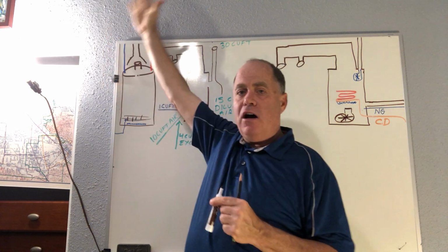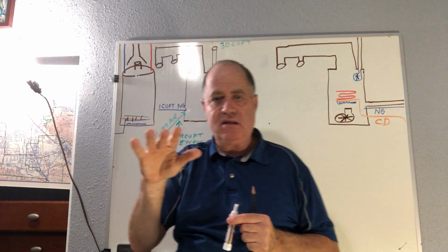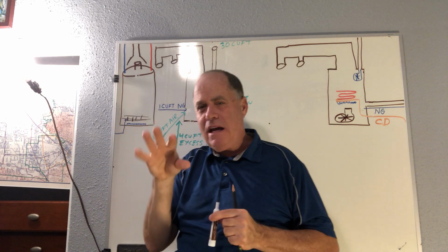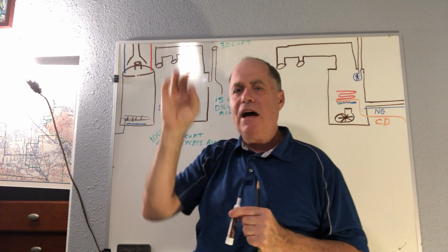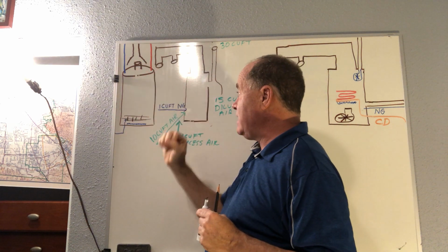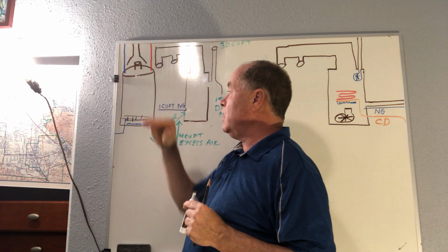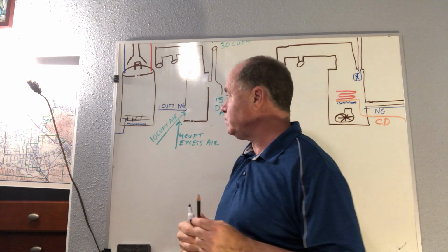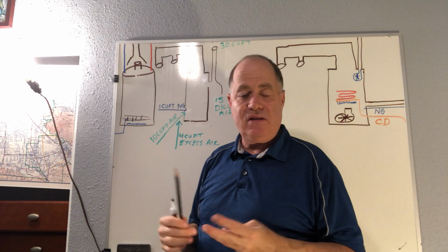So to help it move along and not condense, and sometimes you may hear in an old hot water heater or a furnace a sizzling sound. When it first starts up and gets going, you may have a little bit of condensation where water droplets drop out of the flue pipe, the chimney pipe, back down, and you could hear it sizzling. We don't deal too much anymore with natural ventilation type furnaces.